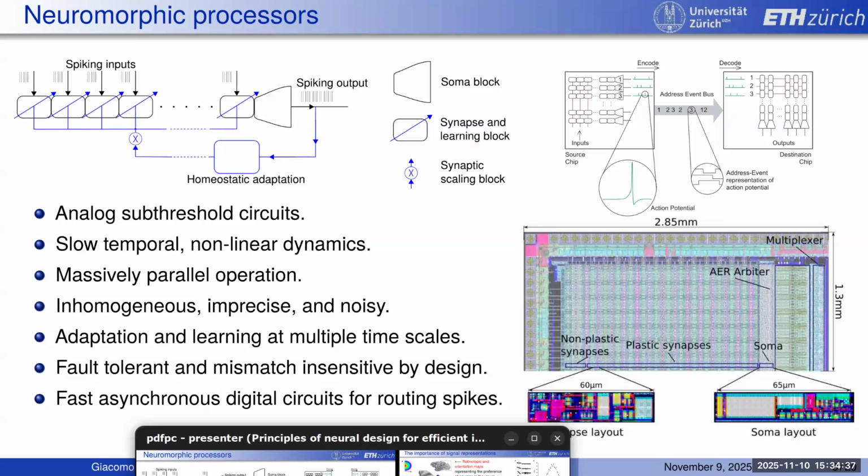If they have learning, the weight changes with the conditions, the pre and the post, and maybe the calcium variable or the calcium concentration that could be stored on a capacitor. And so then we can also copy paste those synapses. So now if you think about it, you have a huge synaptic matrix that is an intelligent synaptic matrix with memory, because every synapse has its own local memory storage, its local calcium buffer.